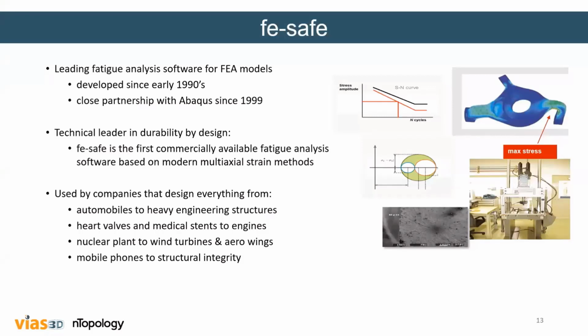In many places we actually use more Excel spreadsheet kind of analysis, but there is a lot of complexity in a fatigue analysis. Just getting the stresses and strain is not enough. You have to look at different planes, especially if there is multi-axial loading, and all this complexity is there. There can also be plasticity, plastic response, which changes things. There is a correction to your fatigue life and all.